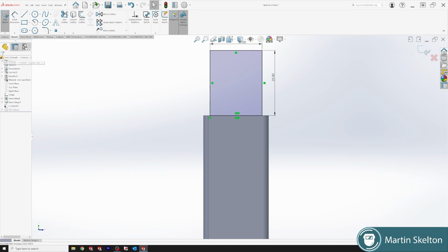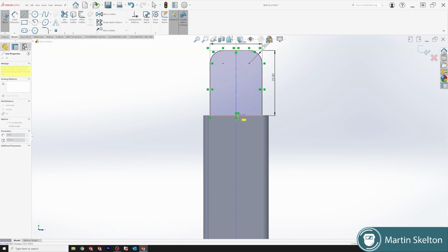And we close. On our drawing, we have 5 millimeter tabs this side. So you click, click, click, and click. And that gives us our tab. On our tab, we have a set of base holes. So we click off our fillet sketch. And we want the center of this component to here.